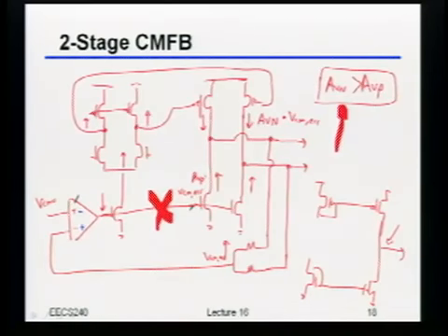So when we have both positive and negative feedback, how careful do we need to be about the bandwidth? Okay, so certainly this had better be true at DC, but not only that, it had better be true across a wide range of frequencies, right? Because if there's some frequency where the positive feedback actually wins, you could indeed have something that just likes to oscillate at that particular frequency.